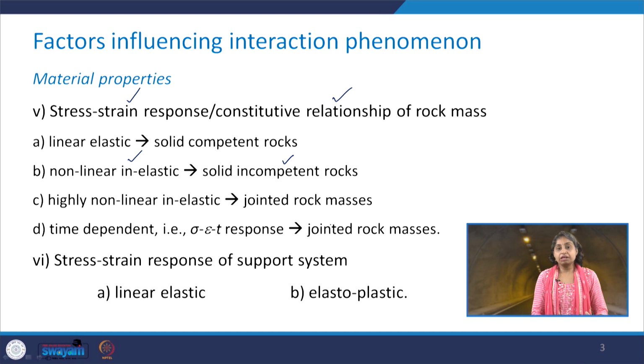In case of the jointed rock masses, it can be highly non-linear inelastic, or you may observe the time dependent behavior as well. That means it will not only be the stress strain response, but we will say that it is stress strain time response, because the stress strain response is time dependent.